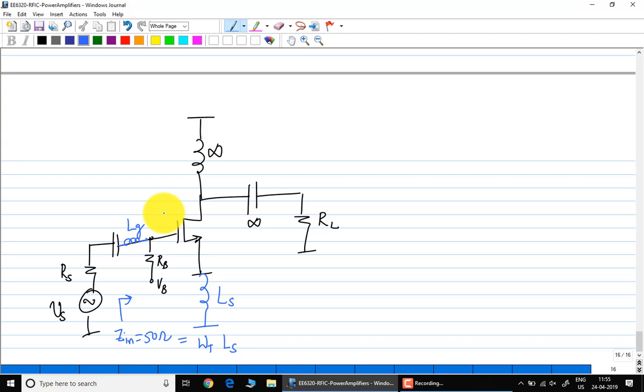Well, of course, the signal current will actually flow through LS. So what will be the voltage developed here? If this is a sinusoidal signal current, you will now get a sinusoidal signal voltage across LS. That current has to flow through LS. Now this is going to affect your output swing. Earlier you assumed the source of the transistor was at ground, so the output can go down all the way to VD sat. Correct? Okay.